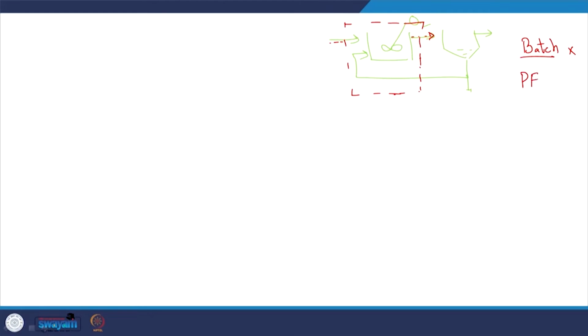Is it a plug flow reactor? Well, with a plug flow reactor, the concentration of the compound of concern within the reactor is not the same throughout the reactor, but here with continuous mixing, and the assumption that we are mixing it homogeneously, we are assuming that the concentration is the same within the reactor. So, it is not a plug flow reactor. So, what is the next aspect? Mass is coming in, mass is going out, reactions are occurring, and more importantly it is completely mixed. So, we are assuming it is a completely mixed flow reactor or continuously stirred tank reactor, right.